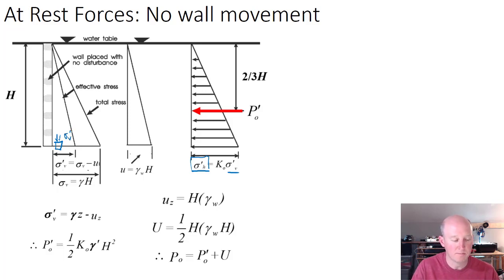And it's got to be prime. And so, hopefully from soil mechanics, we remember how to calculate vertical pressure. It's just the total stress minus the pore pressure. And you see that calculation play out here. And it even shows you how to calculate the force for water pressure also. So we just went through this example.